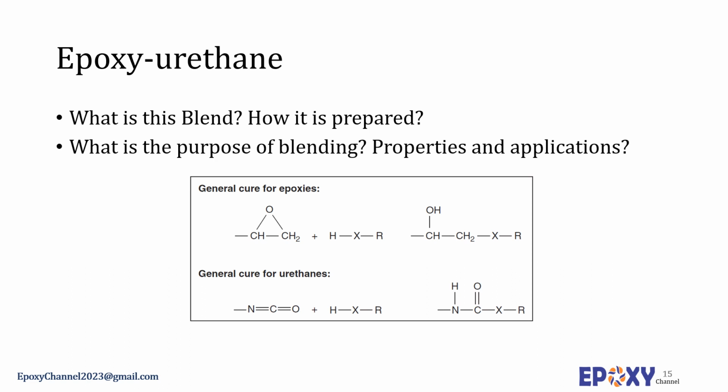Epoxy-urethane adhesives provide properties when cured that are similar to those of epoxy nylon adhesives, except they offer a major improvement in moisture resistance. Isocyanate monomers and prepolymers react with the hydroxyl groups on epoxy resins to give tough, flexible hybrids. The reactivities of isocyanate and epoxy resins are similar in that both can be cured with amines or other hydrogen-containing compounds. The epoxy-urethane adhesives have been noted for their excellent adhesion to many high-energy plastic substrates and for their propensity to bond to oily metal substrate.